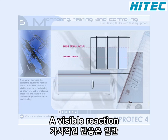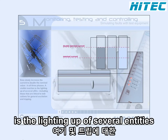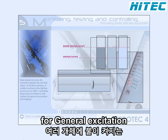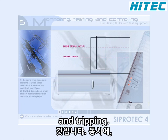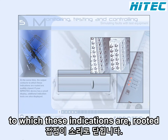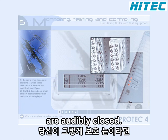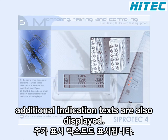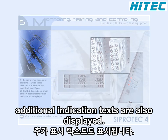A visible reaction is the lighting up of several LEDs, including those that are linked to indications for general excitation and tripping. At the same time, the output contacts to which these indications are routed are audibly closed. If your SIEMENS device has a small display, additional indication texts are also displayed.